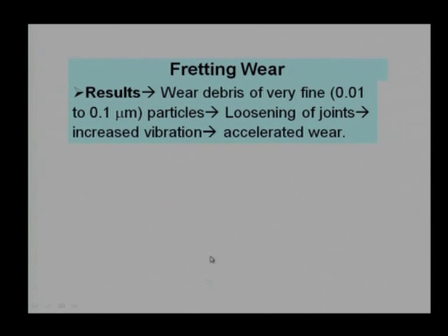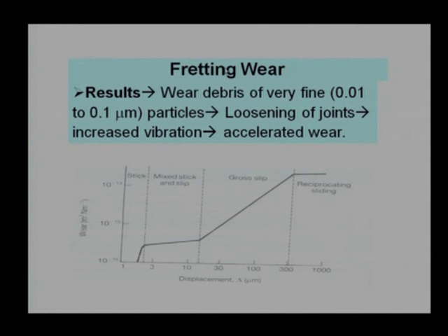And that is why I am saying that fatigue happens something like that. Initially there is a stick phenomenon, we are pushing it to a certain value and relieving the load. We are not doing it intentionally, but load is coming from outside from other factors that will cause some slip, micro slip, and initially the slip is of low magnitude, slowly the material is getting removed from the surface, the slip will turn out to be gross slip, and this gross slip is harmful.